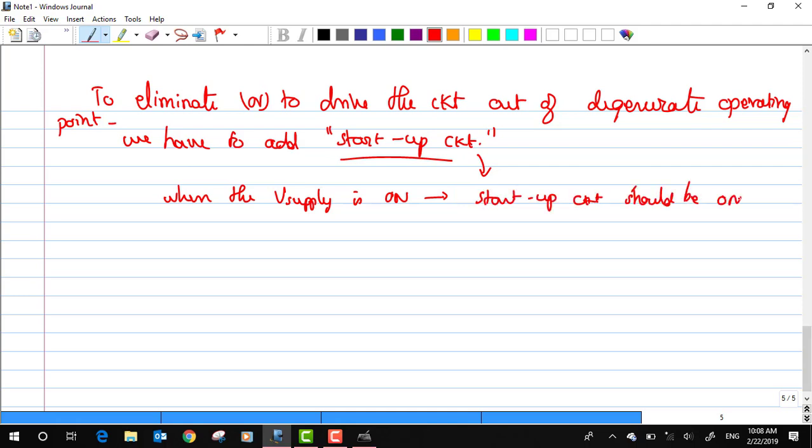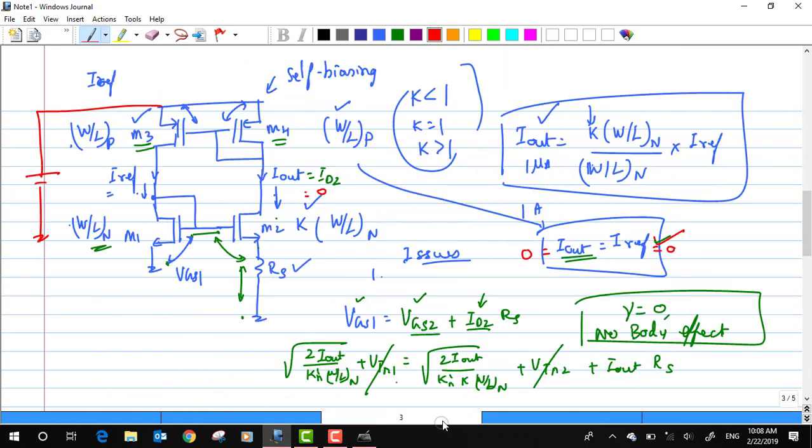This is one of the important properties that I need to satisfy, and the moment it starts on, it helps make these transistors, say for example M3, M1 and M4 and M5, go to saturation condition, okay.